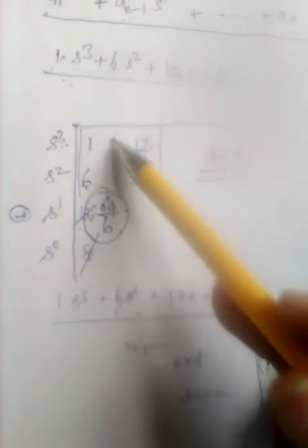This is what I want to prove using the determinant method, which is quite advanced compared to the simple quotient method. This is the quotient method of rearranging the polynomial into the Routh-Hurwitz table, but this is a determinant method of Hurwitz analysis along with the Routh criterion in extracting the coefficients or roots of the polynomial in determinant form. This is one simple example we have seen. Now we are going to see some concepts related to the same.